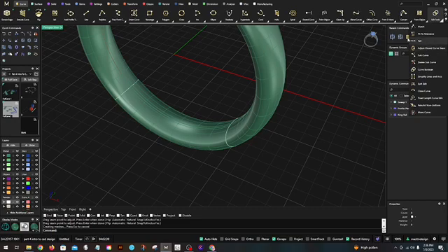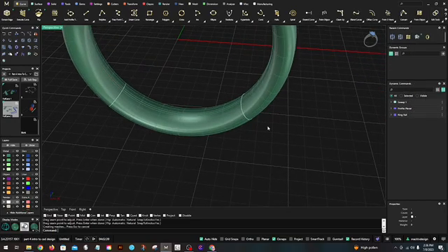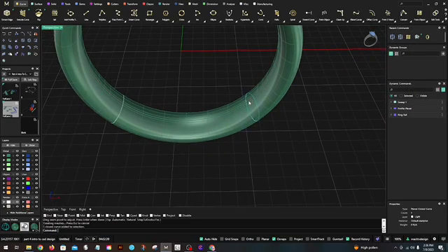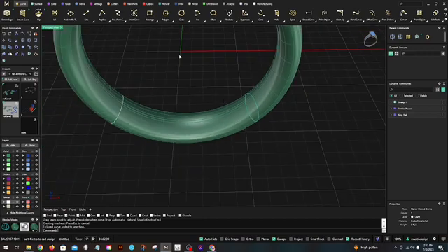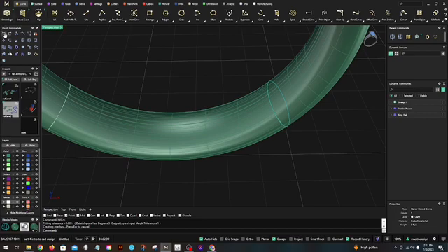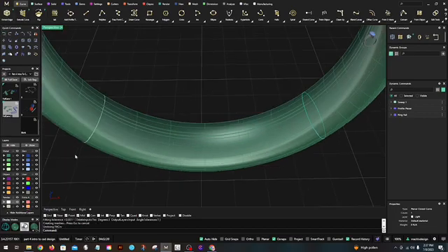That one was called adjust closed curve seam. Now the fit tolerances, sometimes you'll need to take a profile, and I just type in fit curve, there we go. And did you see that? I'm going to back up. All right, and so I'm going to do both of them at the same time.